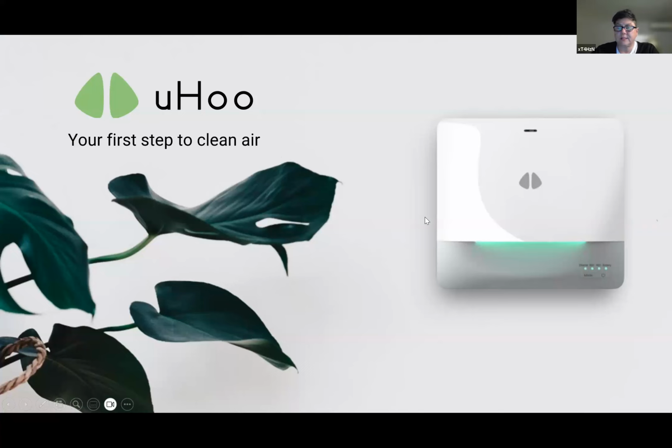Indoor air quality systems. Some of you do use this, especially if you're going into a customer, and this is only one of the brands. There's more brands than that. But an indoor air quality meter is very good, especially if you're looking at living conditions of your customers. Most of them do have PM 2.5, TVOC, temperature, humidity, and the Yuhu has 13 parameters.